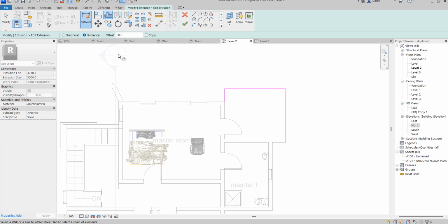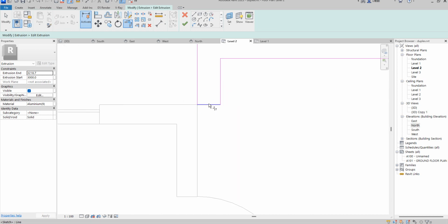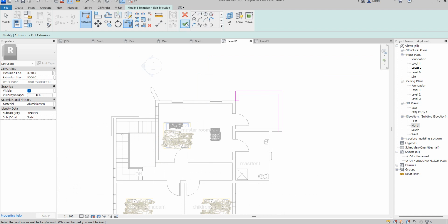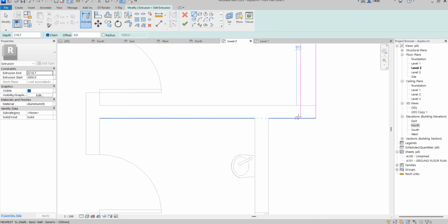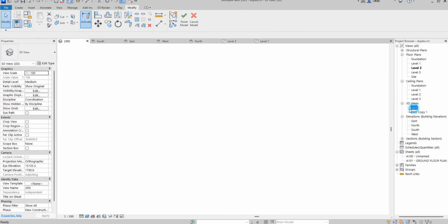So what I need is to offset 225 for the thickness. So okay, press it. You don't need to press enter. No, it's copy. You're going to see with copy. So click on with copy so that you have it duplicated. So same thing you have here, same thing. So you trim this up, so you get now. So you do the same thing here and you fix this. So if you finish it now, something is okay. So you just need to draw the line, join them together, because it's an open loop. So click finish. So now go to 3D and see what you've created.